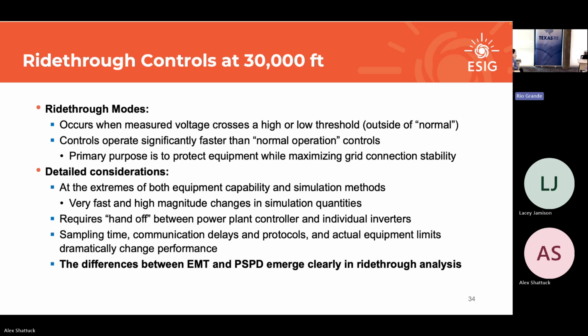And a half a second is not out of the realm of possibility, especially if you have a plant controller, an RTAC for switching capacitors or other devices. You might have two plant controllers who need to talk to each other. And then if you actually go the real academic way, then it's all the error, right? Because then it could be, maybe I sampled that 1 millisecond of a 40 millisecond window, and now up to a second, just communication time.